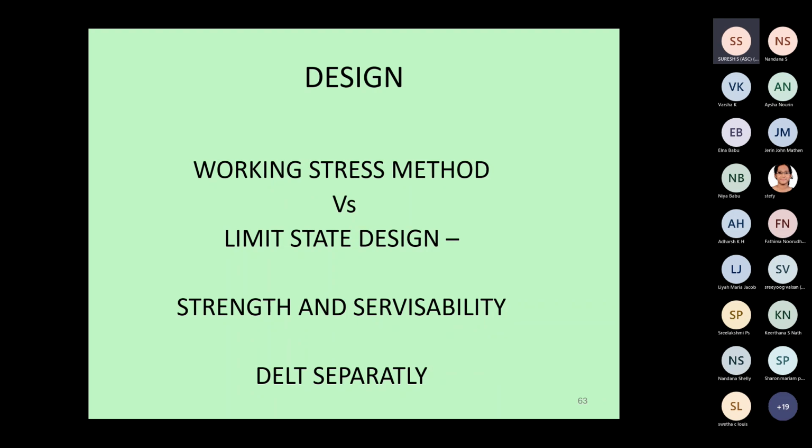So we do this for bending, we do this for tension, we do this for compression, direct compression, bending tension, etc. And we treat the concrete as a material which is primarily expected to carry compression only. So we treat the allowable tensile stress in the concrete as always 0, even though it is not. It can carry a certain amount of tension, but we neglect this in the design process.